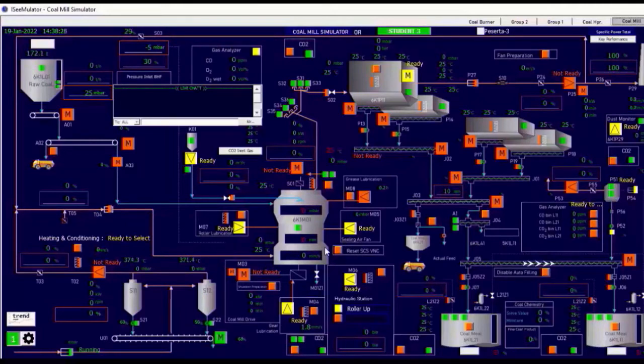From this configuration, in general you can see the main tool for grinding raw coal, which uses a vertical roller mill, then a dust collector to capture the fine coal product, which is then put into the fine coal bin. In this simulator, also equipped with product quality control, which is controlled is residue or sieve value, and also moisture content of fine coal. Then in the lower left corner of this display, there are settings that are used to control the running of the simulation.